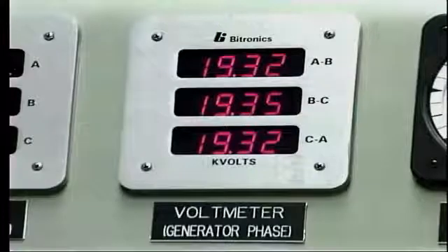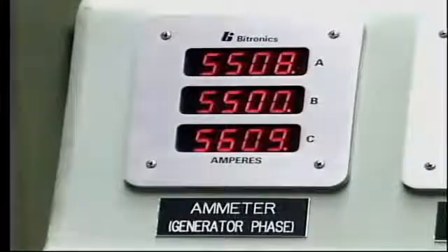One problem that can occur on generators is the loosening of the windings with resultant vibration and increased temperature rise and perhaps damage to insulation. Checking the conductor wedges for tightness is an important maintenance item during overhauls. The stator conductors are connected together in various series and parallel arrangements to produce the rated terminal voltage, typically in the range 11 kilovolts to 25 kilovolts, and rated output current, which may be several thousand amps.